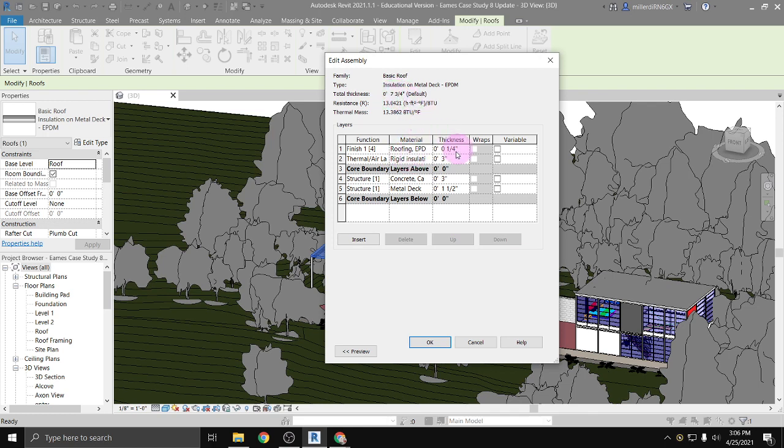Not only is it telling me the actual dimensions of the different pieces of material that are being used as opposed to nominal dimensions. So if I had pieces of wood in here, I wouldn't have that 2x4 defined as 2 inches by 4 inches. I would have it defined as 1.5 by 3.5. But I have all of my thickness here, which is going to be important for measurements regarding construction. But I also have all of my different materials defined.